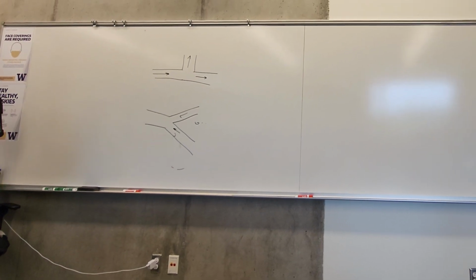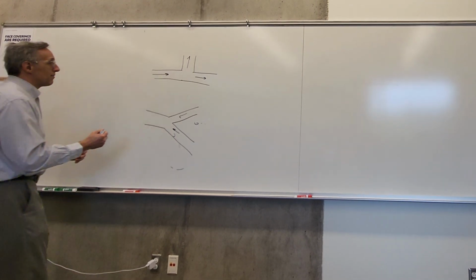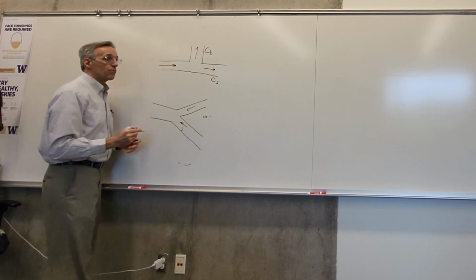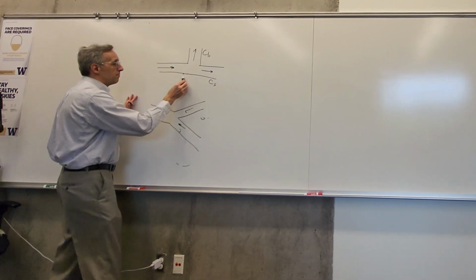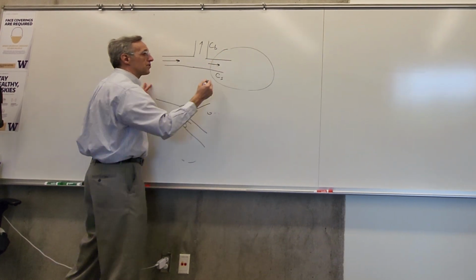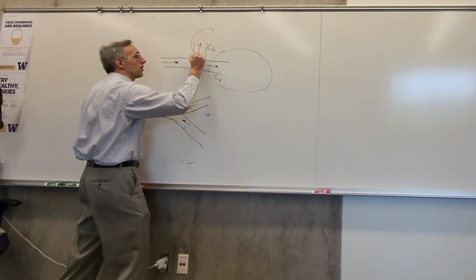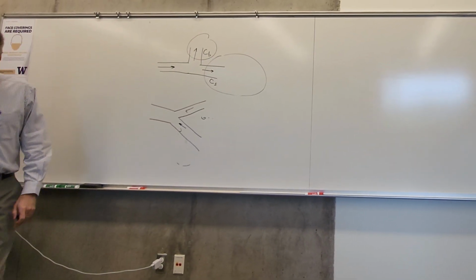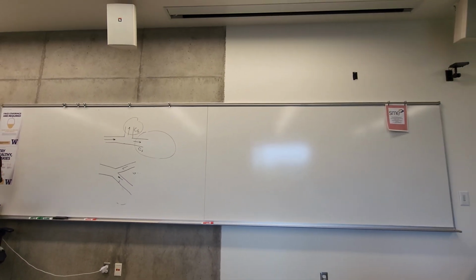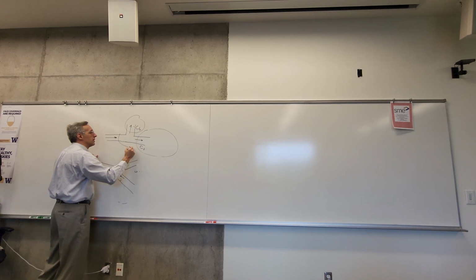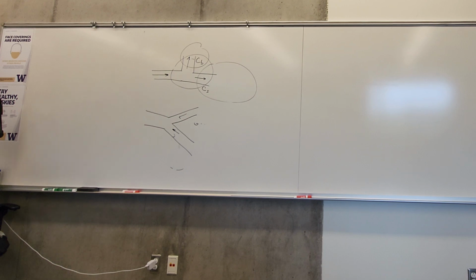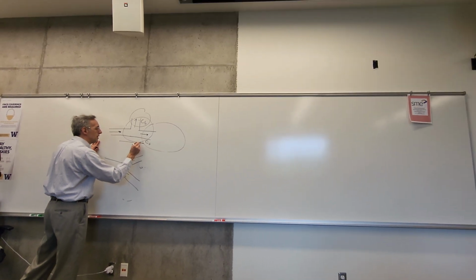If we have the loss coefficient method, we typically will have a loss coefficient for the branch and a loss coefficient for the straight through section. We'll take this loss into account when we're studying this segment, and we take the branch loss into account when we're doing that segment. In the homework problem, you just had an equivalent length, and if you have the equivalent length for the fitting, you only use that once. And typically for a T fitting, you use that on the straight through segment.